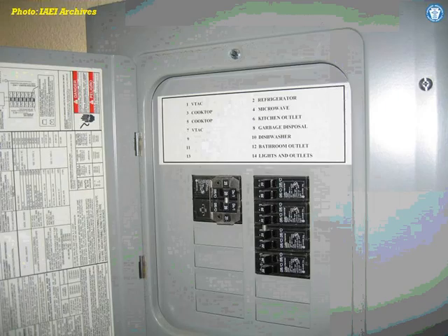Circuit breakers, guys, also have to have a directory that indicates which circuit is feeding which. And if you have a spare, it should say spare. If you have a spare circuit breaker, you shouldn't say Chad Kirby's office, because he could be fired tomorrow, and nobody after a couple of years knows who Chad Kirby is. It came in 2008. They said it can't be a transient name, it has to be a solid name, you know, a name like room 114.